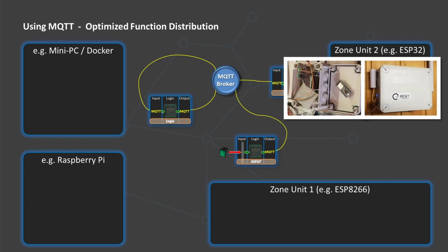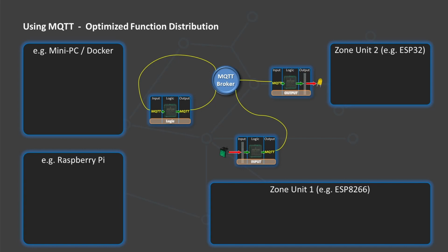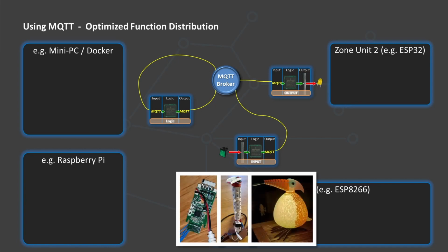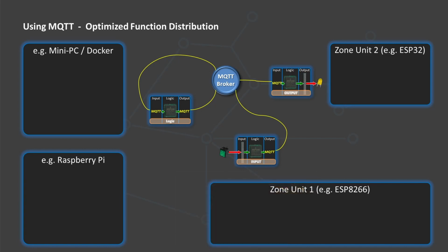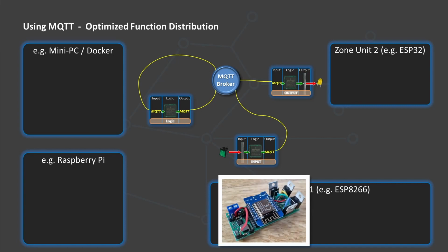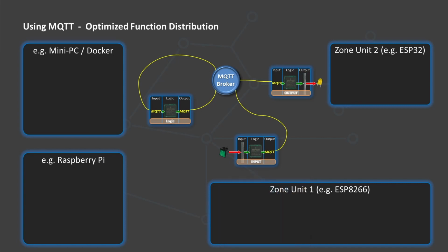All these modules can certainly still be physically located within one common device like the Raspberry Pi, but even then they communicate exclusively over MQTT. The broker can also be located within that same device. A later separation and removal of any of the modules into another device is always easily possible.